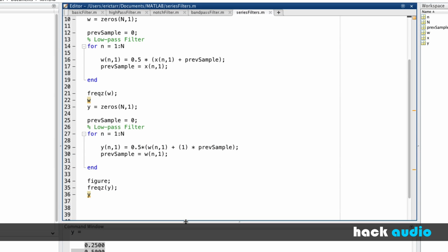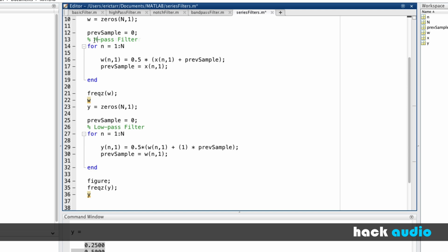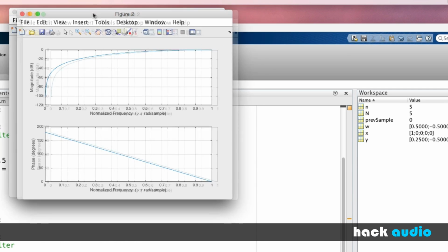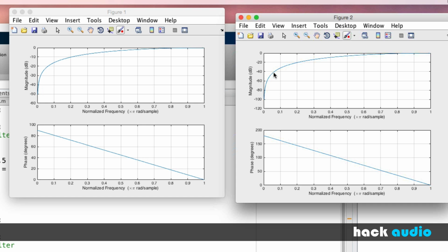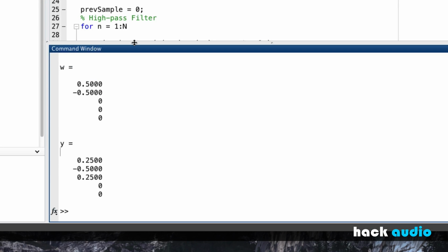So let's recreate this process using 2 high-pass filters now. So let's switch this over. See that we end up with a very similar kind of result or complementary kind of result. 2 high-pass filters. So this one should have a gain here of -1 multiplied by the previous sample. And this one should also be -1 times the previous sample. Do this again. We've got high-pass filters, extra attenuation over here for the combined series high-pass filters. This is just a single one. And similar thing happens for our impulse response. We've just got 1 sample of delay here. If we want to have a sharper high-pass filter, we need to have a higher order, -0.5 and -0.25. If you remember from our low-pass filter what the impulse response is, now compared to our high-pass filter, it's again complementary. The only difference was this second term was negative. So there is some relationship between the low-pass filters and the high-pass filters.